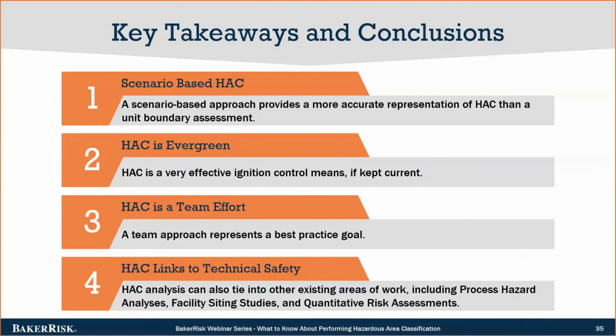As we pointed out, this allows a detailed understanding of what is involved with the actual hazardous area, both in terms of the materials and the electrical equipment and the processing equipment that's all involved with that. The unit boundary is just taking a very broad approach, and it's very difficult to determine what is the driver unless you're just doing very conservative approaches and not interested in the details. However, unfortunately, the details are very important, especially if you're looking at the life cycle of a production facility.